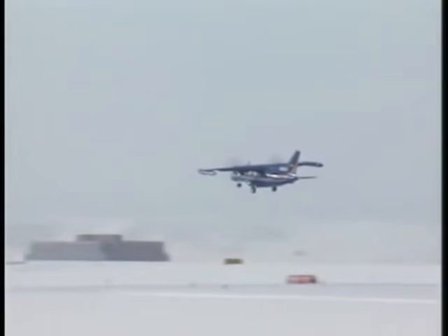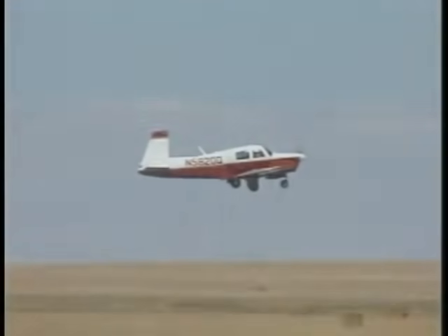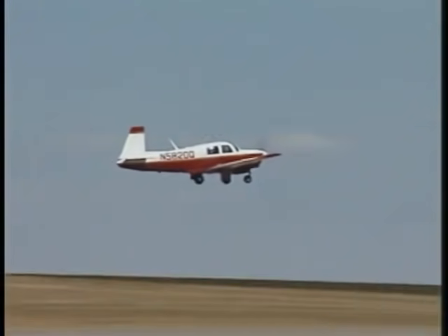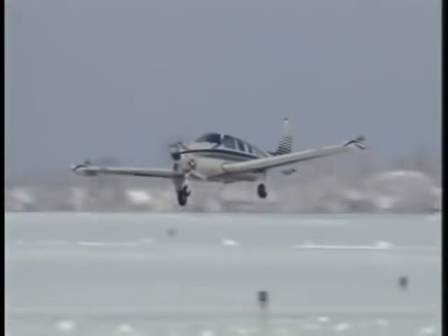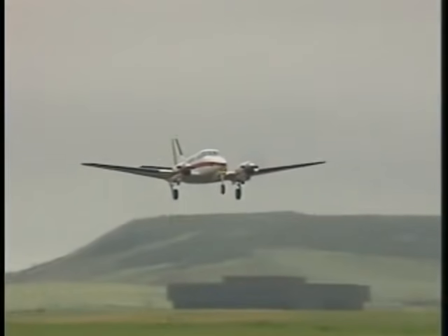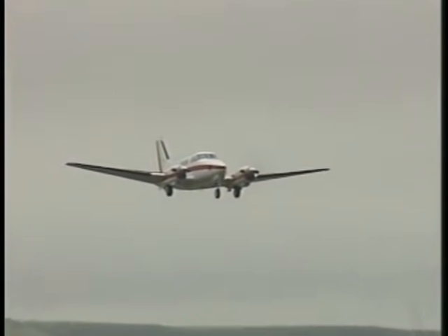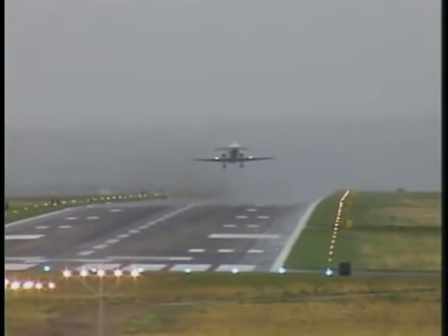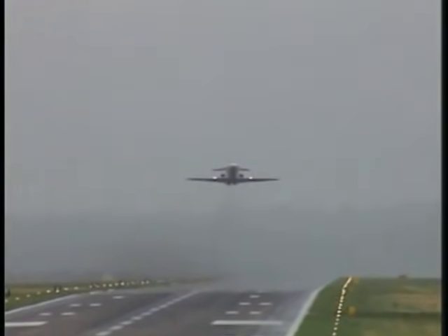To expedite an orderly and safe flow of IFR departures at busy terminal areas, Instrument Departure Procedures, or DPs, were created. These procedures and charts simplify departure for you and controllers, provide a transition between the airport and en route structure, as well as reduce frequency congestion.